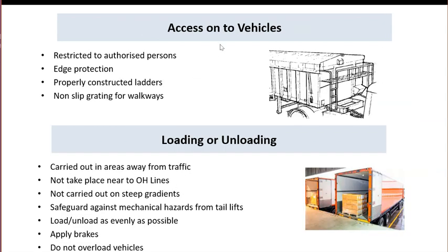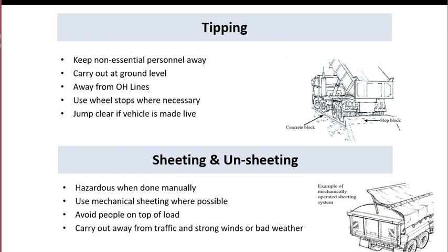Access onto the vehicles must be restricted to authorized persons, with edge protection and also a proper ladder. Loading and unloading should be carried out away from the traffic, and it must be level and safeguarded against mechanical hazards from the tail lift, and apply the brake. Do not overload the vehicles.